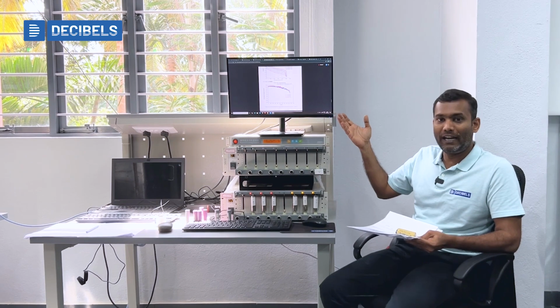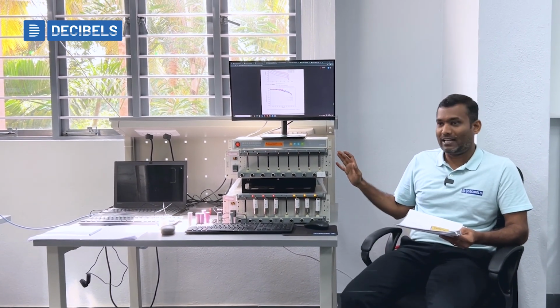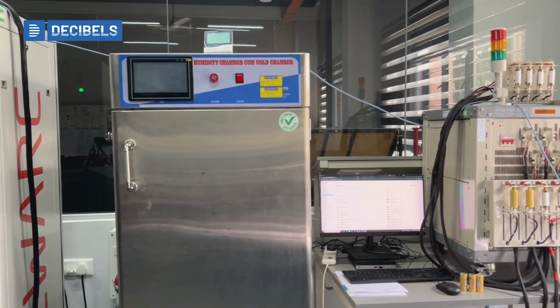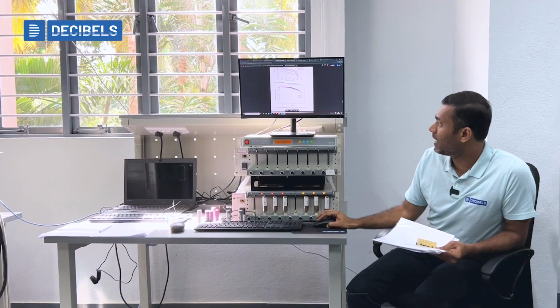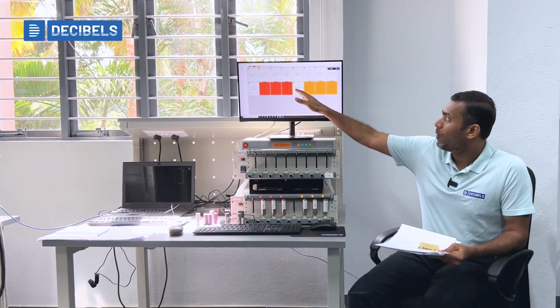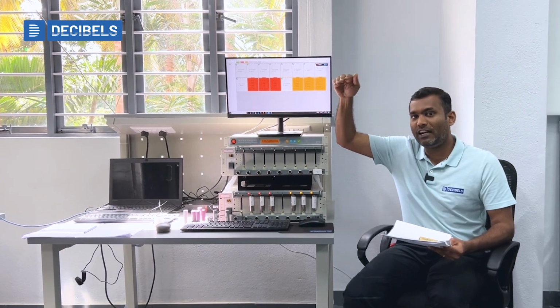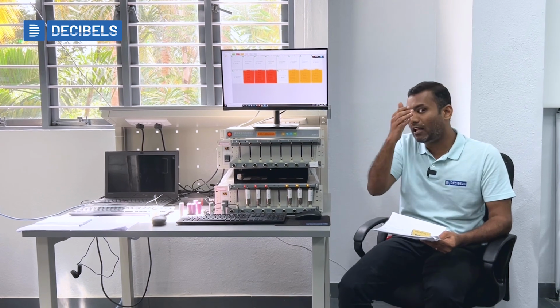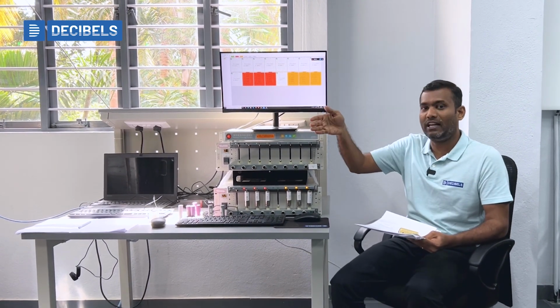So how do you perform a capacity test? We need to use a machine like this if you just want to do a charge and discharge test. But if you want to perform it at different temperatures, we can use thermal chambers, keeping the cells inside a thermal chamber and doing that test. We can go to the machine characteristics. There we can set at what C rate it should charge, what C rate it should discharge, and what the rest condition between charge and discharge should be, and then we can perform this capacity test. We can increase the C rate and study the characteristics.